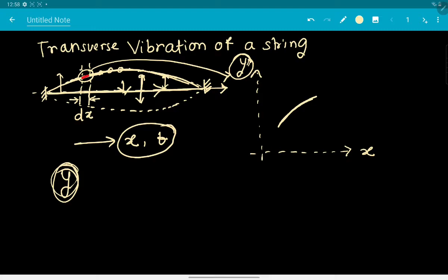This y is going to change for any particular time along x, and at any particular x, let's say if you are standing over here, this is the point which is fixed. If you are observing it for a good amount of time, then you will be able to see vibrations at that location. That essentially means that the string element at that location is changing its displacement with respect to mean position as time progresses.